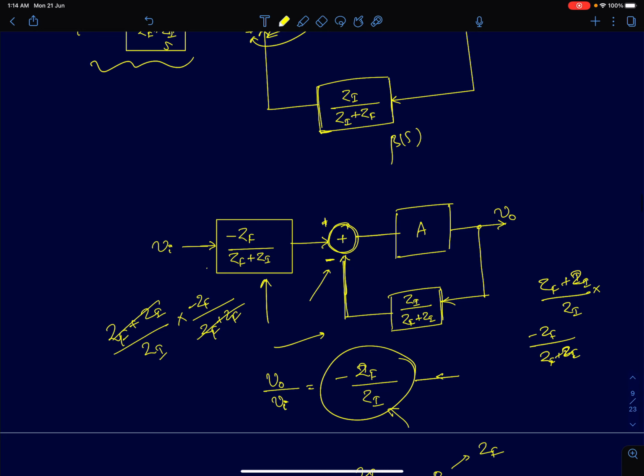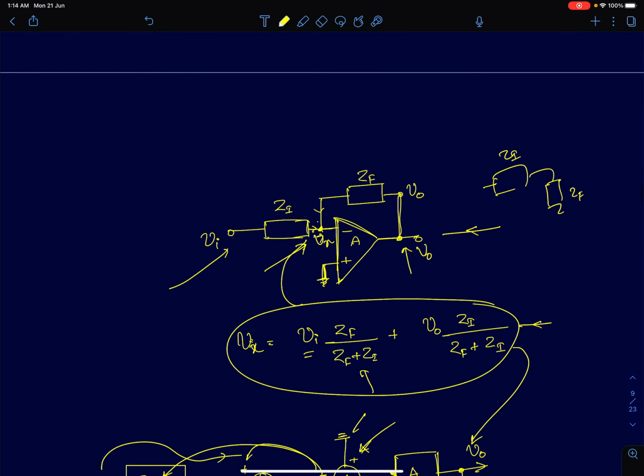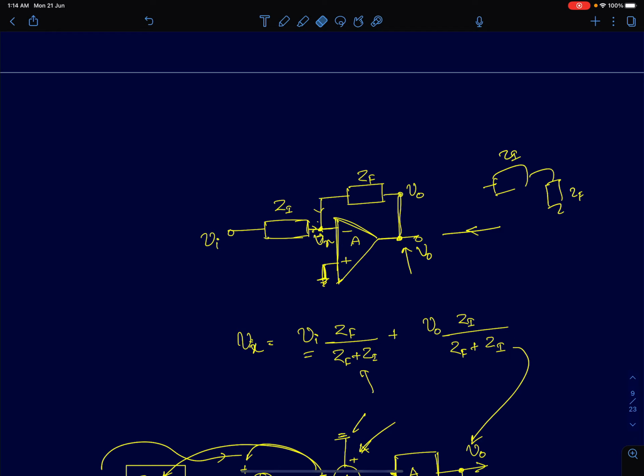So using this, we'll quickly see some circuits, but a point that I want you to remember, which we will talk about in greater depth in the next lecture, is that the voltage at this node is at ground. It can be an AC ground or a DC ground. Then this node Vx, if there is negative feedback in the circuit, we just saw the error has to be 0, which means Vx has to track the positive terminal. So that will also be at ground.